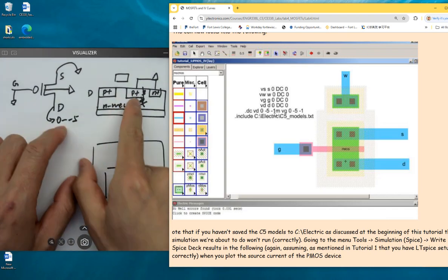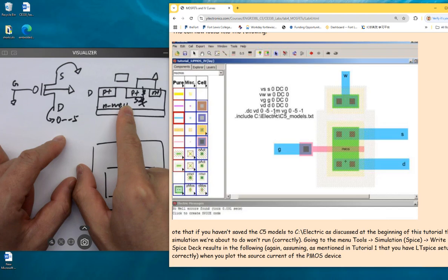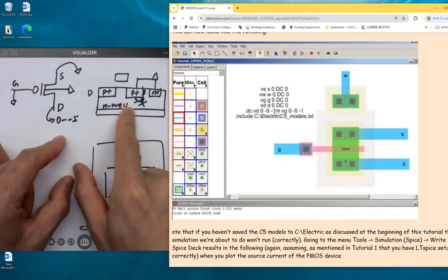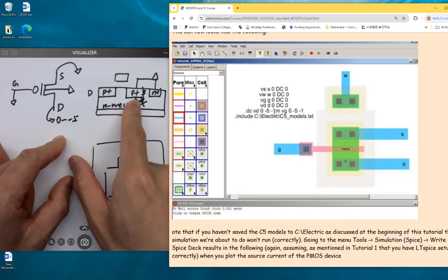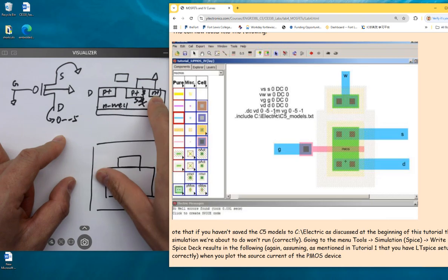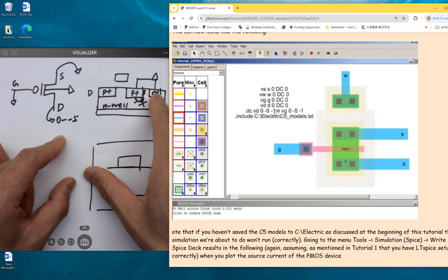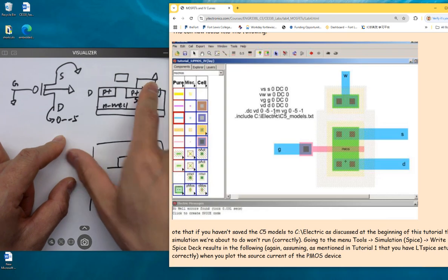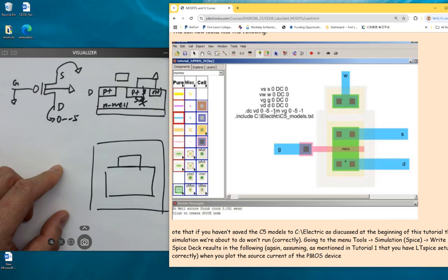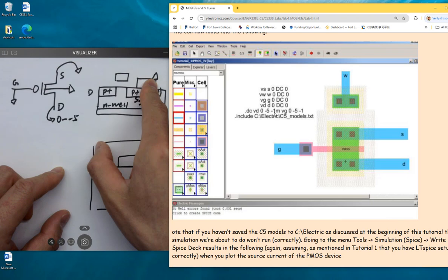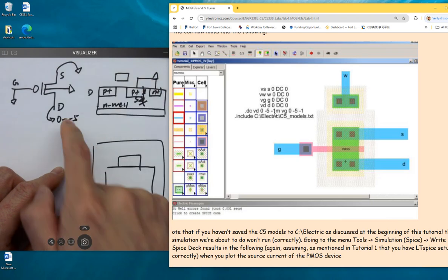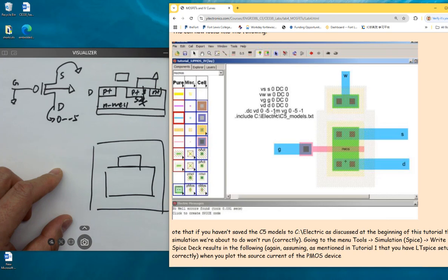So look at this. Remember P-N junction, right? So P and N form a diode. So that's why we want to short the N well to the highest potential of the circuit. But now you're grounded. Why? It's just a simulation. Is ground still the highest potential of the circuit or no? Yes, it is. See?